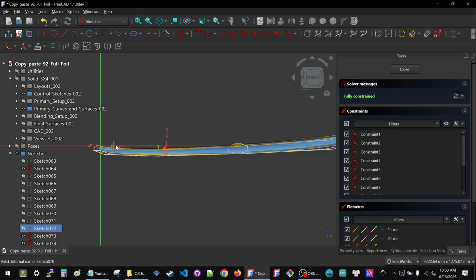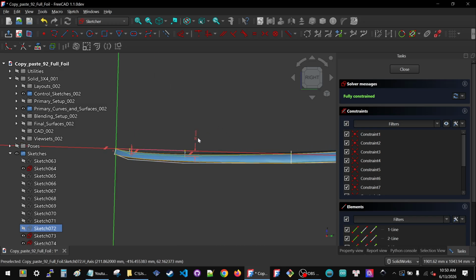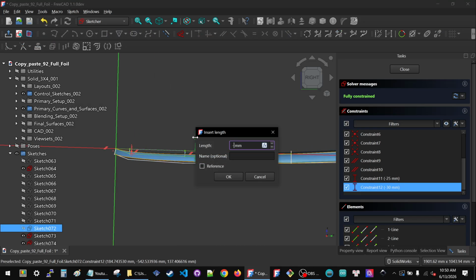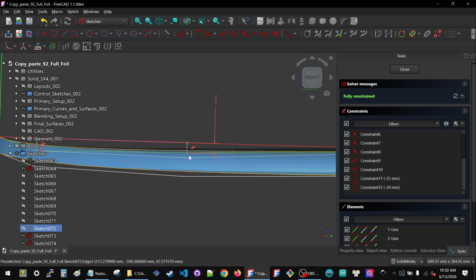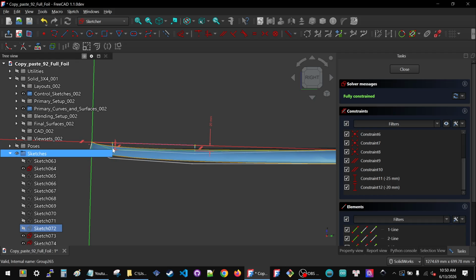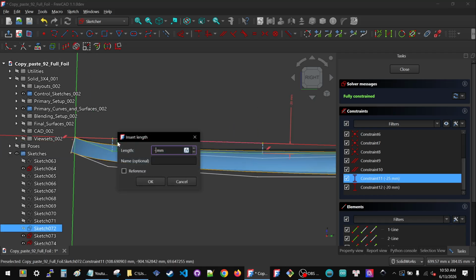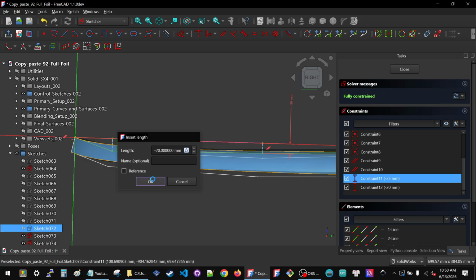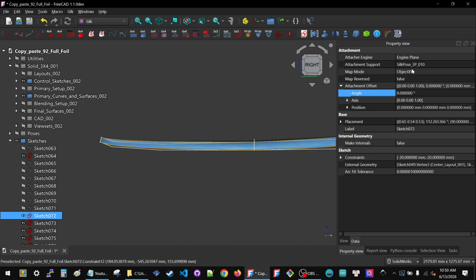Open the sketch. Now I'm in the view of that sketch, which is very close to the right view, but not exactly the right view. I'm going to switch to the right view. And here I'm going to say this minus 30, let's try minus 20 instead. Okay, that brings it up and that thickens it. I think that looks about okay. And at the end, does it need to go down this sharply? Let's try minus 20. Okay, I like that. Minus 20, minus 20.